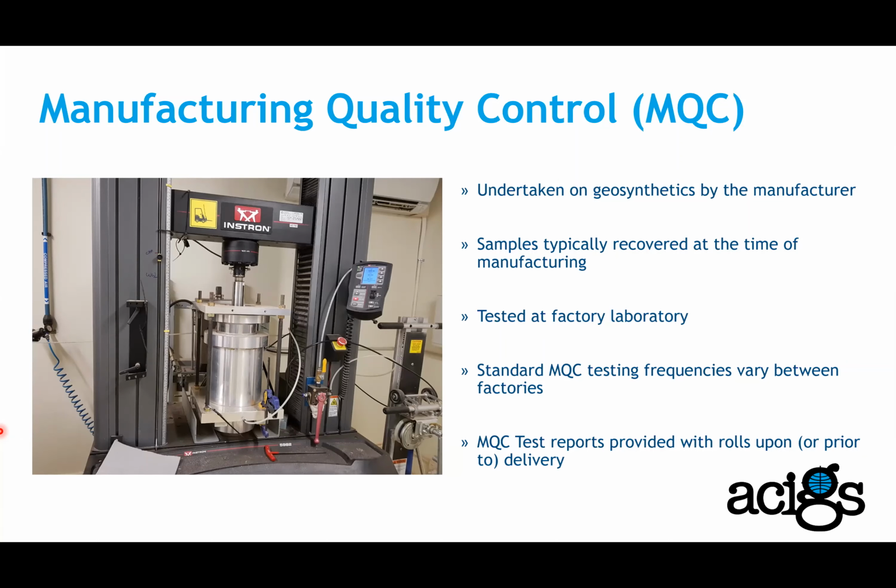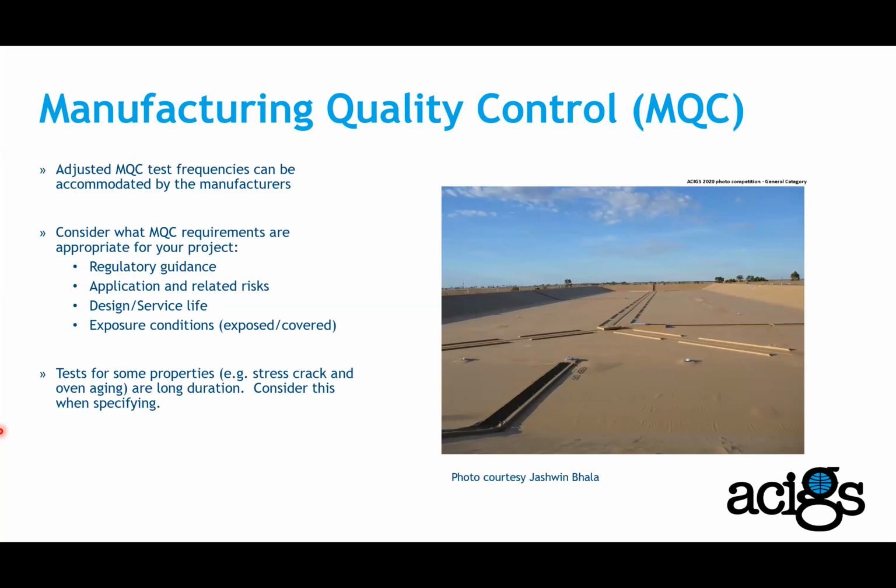So adjusted MQC test frequencies can be accommodated by the manufacturers. As I said, some manufacturers use different frequencies for the testing. Consider what MQC requirements are appropriate for your project: regulatory guidelines, applications, and related risks, design or service life, which is a very important factor, and also exposure condition, if the material is going to be used in an exposed or in a covered or buried condition. We should consider these factors when we decide on the requirements for the frequencies.